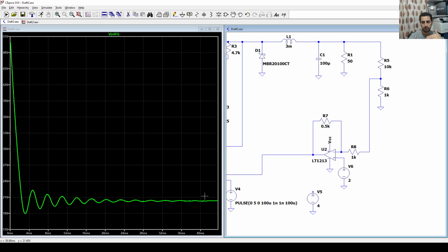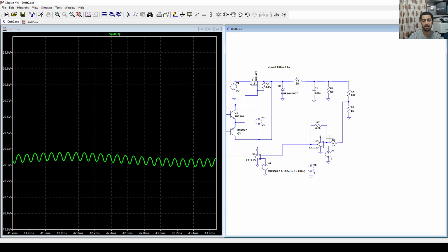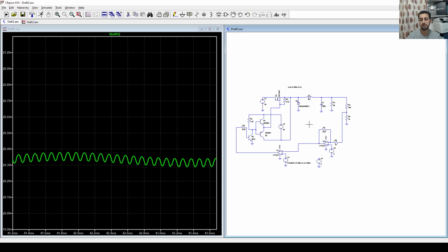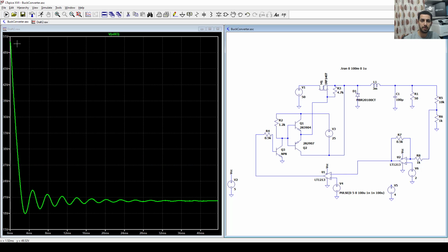Okay. Yeah, 20.3. Okay, which is good, acceptable, but implementing PI control makes the steady state error maybe less than this. Okay, there is a note here, which is that my output always starts from 50 and goes to the desired value, and that's weird because I think the duty cycle is inverted, and maybe we can fix that.